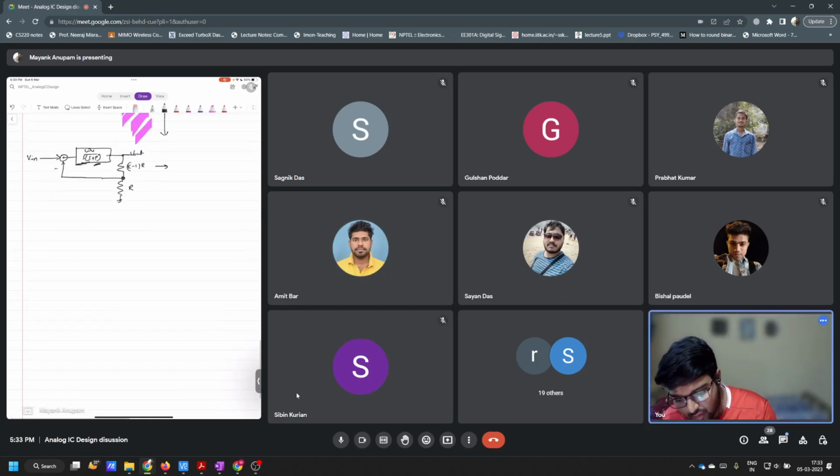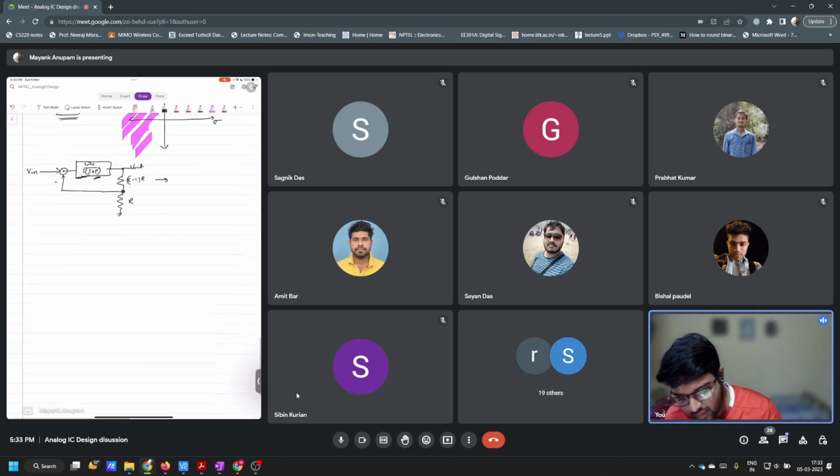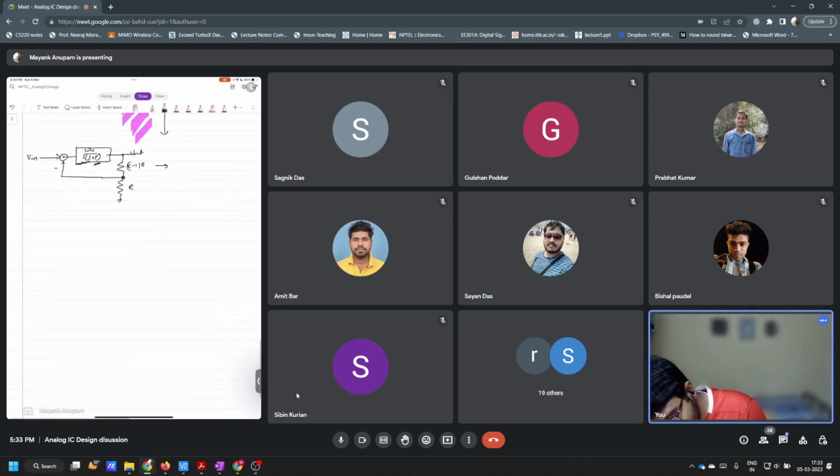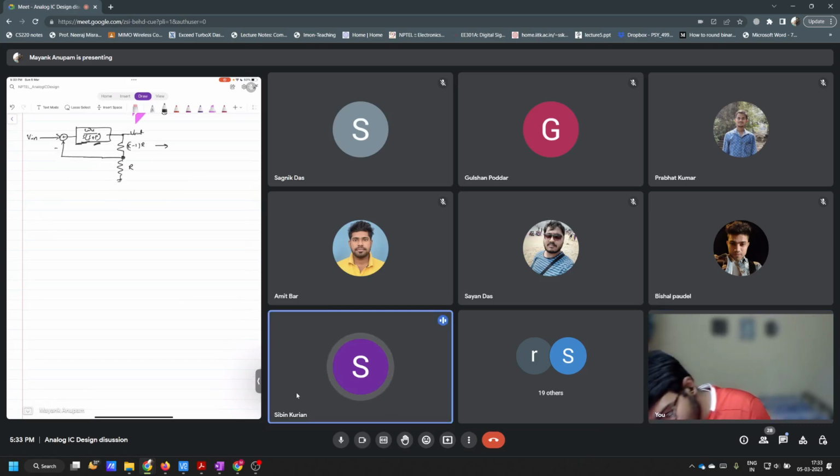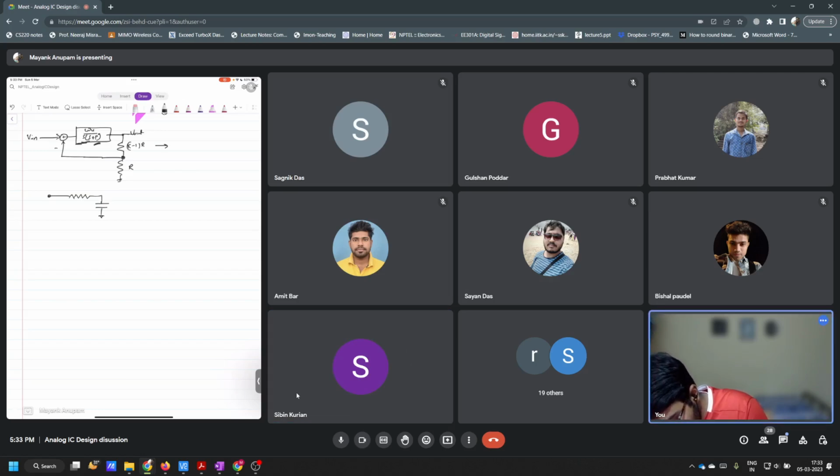And how is the pole adding a delay, by the way? How does a pole add a delay? It's the phase lag. Yeah, time delay because of phase lag. So let's see this. This is V out, and this is V in.